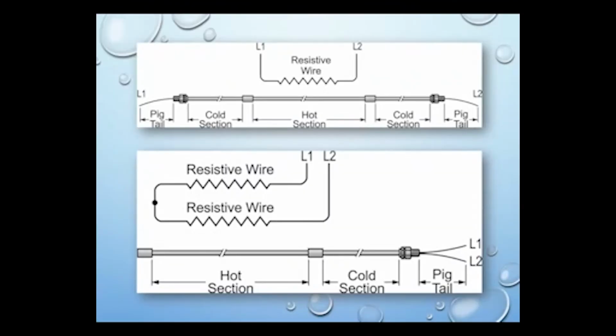The first type is a series fixed resistance, and it is a cable with a set resistance in which, by passing current through it, will create a certain amount of heat. They come in a couple different orientations where we could have a single conductor cable and wind that along the surface which we would need to heat and have it come back into the same location to connect to our voltage source, or we can have a multi-conductor cable that would produce heat along the entire length of it and have itself as a return path.